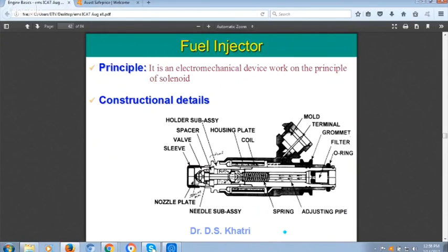And when you are manufacturing this injector, you need grade 7 cleanliness level. Grade 7 means like an OT where a doctor is operating on you. Even the person assembling, you are not able to see their body part. The complete head is covered, eyes, mask, hands, everything is covered. No body part is visible when we are assembling and testing the injector. Because even during assembly, the size of the hole where the fuel is injected is in microns. And if the smallest dust particle settles there, it will block it. So your injector fails at the assembly itself.